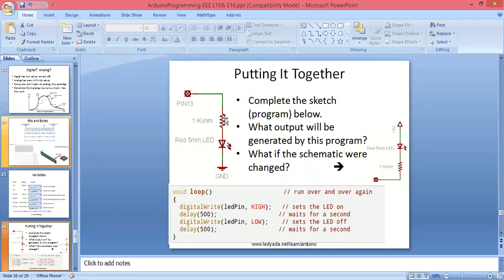Because here we know the Arduino board will give 40 milliampere current, but the LED is not capable of taking that much current. We have to convert that 40 milliampere into 20 milliampere. So we are using a resistor here to oppose the excess amount of current. And we can connect the negative terminal of the LED to the ground terminal of our Arduino Uno board. When we are supposed to write the program, firstly what will we do?